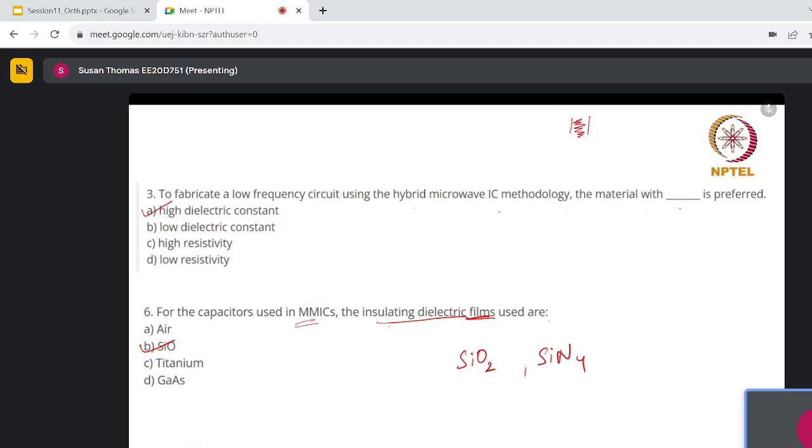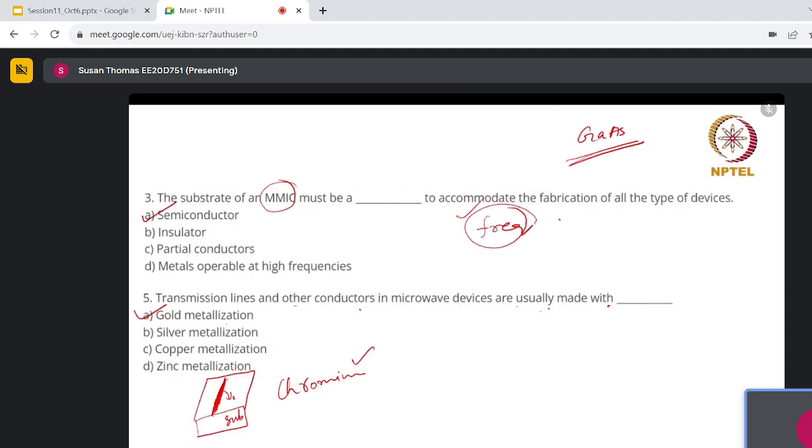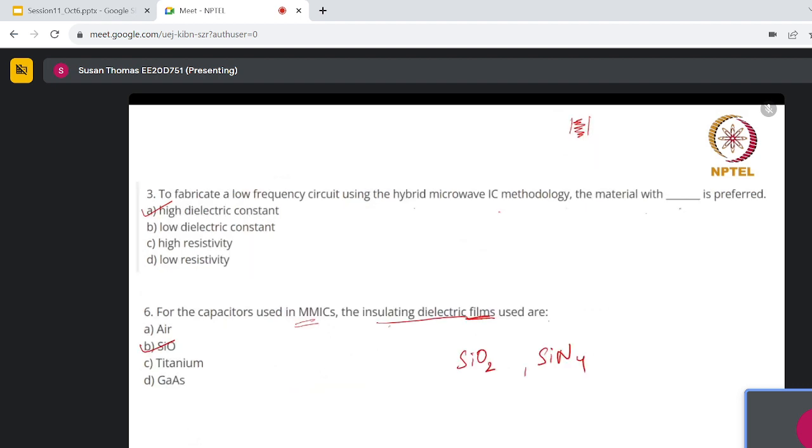Basically, as I told in the beginning, monolithic microwave integrated circuits are built on a substrate, basically a semiconductor, and all the components are integrated on the substrate. So what happens here is they tend to waste a large area of this expensive semiconductor substrate for components such as transmission lines and hybrids. That is one of the major disadvantages or drawbacks of monolithic microwave integrated circuits.